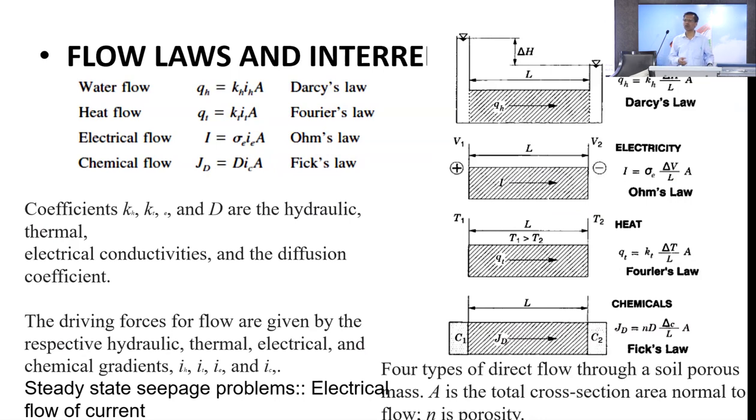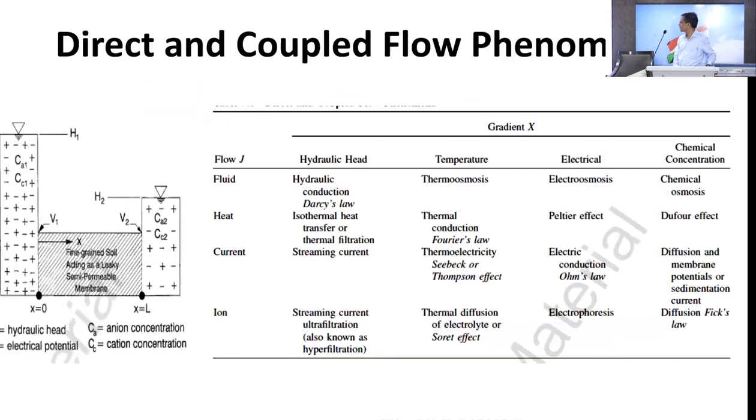So these aspects of flow are now being required in some cases to decant or reduce the moisture to help in consolidation. Because the formula is similar, a gradient is there, a constant and a potential. So people have tried to make it both electrical and hydraulic. Both can work, and if you go quickly, it can also help consolidation, and consolidation is the main part. I will come to that. A flow through consolidation is important.